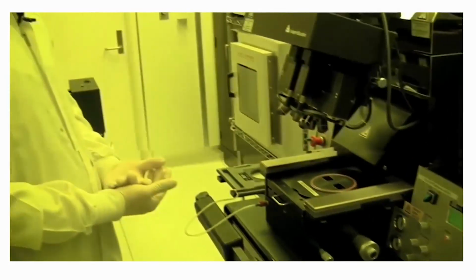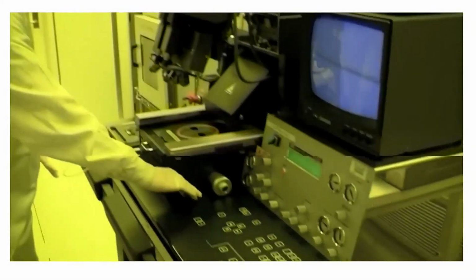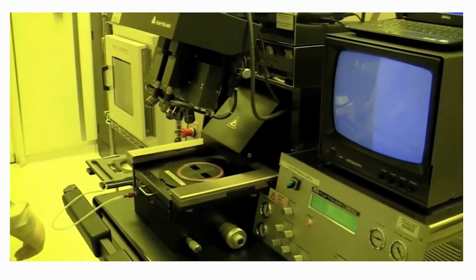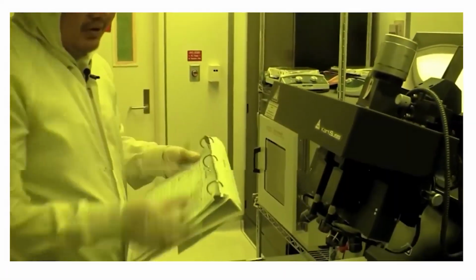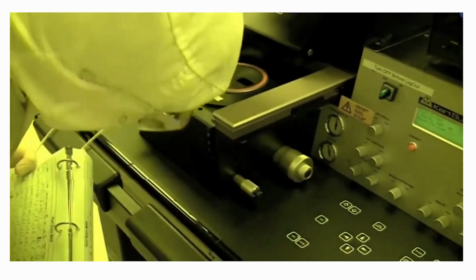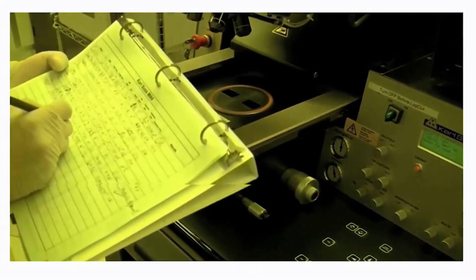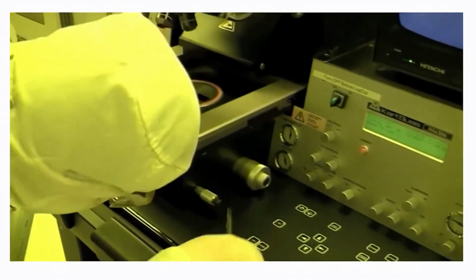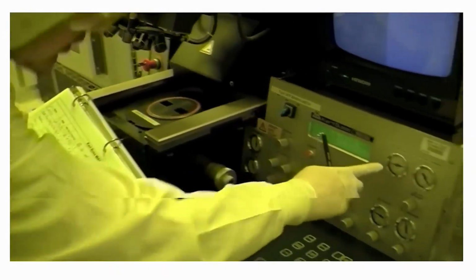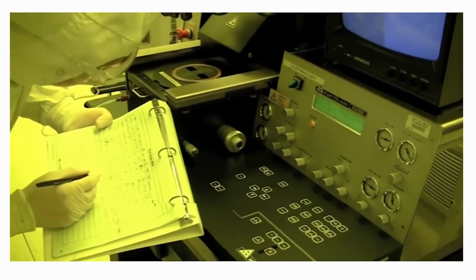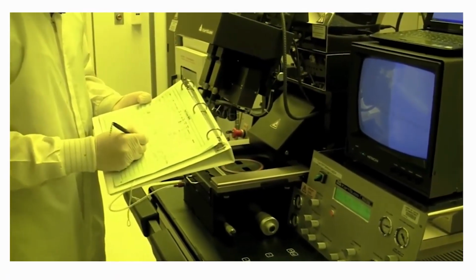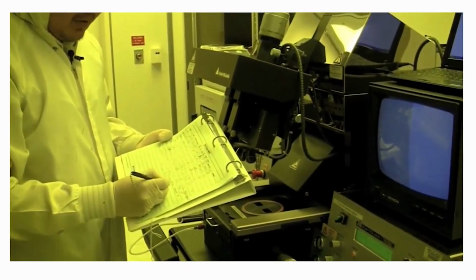So now we're ready to turn the system off. We want to make sure everything's in the standby position that you started the machine with. Before you turn it off, you want to make sure you write in the logbook the different parameters. The compressed air is about 4.9, the nitrogen is about 1.65, the vacuum is about negative 0.86. We used a 4-inch silicon wafer, and we did a 25-second exposure.